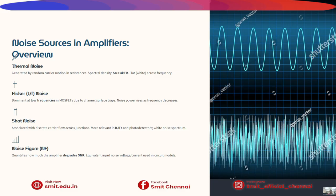It is also known as 1/f noise. It becomes significant at low frequencies and is common in MOSFET devices. The third type is shot noise, which arises from the discrete movement of charge carriers across semiconductor junctions. Noise figure is a parameter used to measure how much an amplifier degrades the signal to noise ratio.